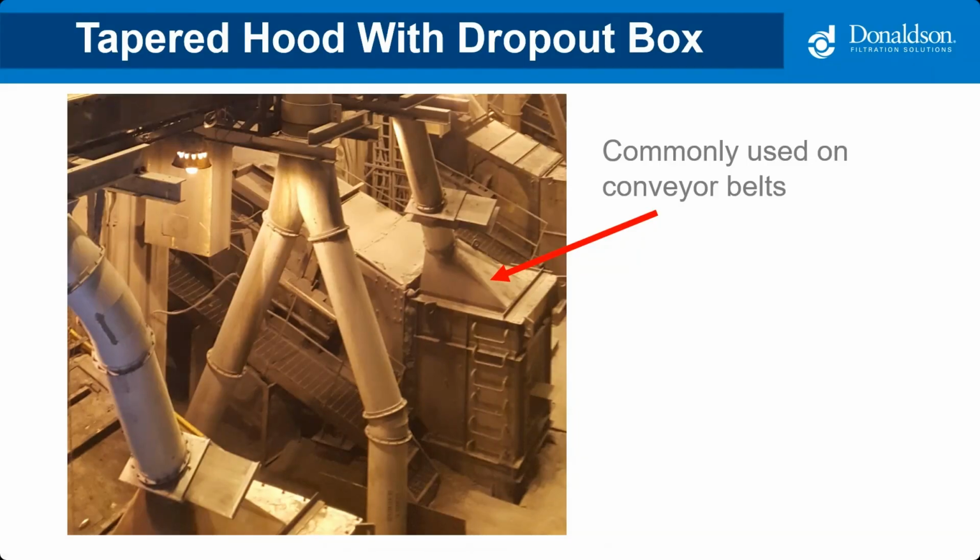So if we reduce the airflow to under 1,000 feet per minute, we're still going to capture the fugitive dust, but we're not going to capture the good product coming up, because we want to make sure that we're not sucking good product into the collector. And then by the time it gets up into the duct, it's just the dust, and then it gets sped up to your carrying velocity, which for an application like this is probably around 4,000 feet per minute.